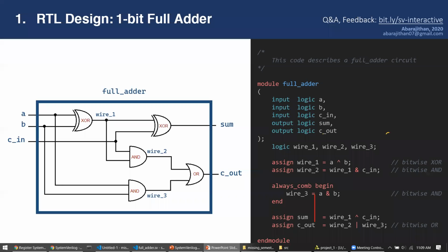If you are creating multiplexers and state machines, case statements, stuff like that, then you need an always_comb statement. Assign is just one line, but inside always_comb you can put multiple lines. That's the idea. But they are both describing combinational circuits. What I'm trying to say is that this statement and these statements are equivalent. There's no difference between them here.